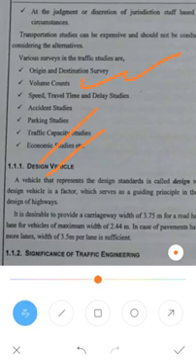One road may have an average speed of 80 km per hour. On some roads the average speed will be 60 km per hour. So different speed, different travel time, and then the delay study. This is another important survey, a deciding factor for whether it can go for a state highway or a national highway.